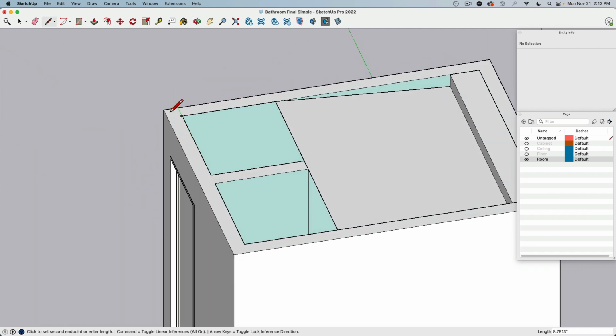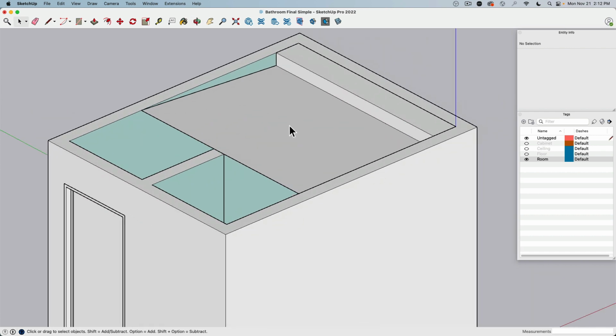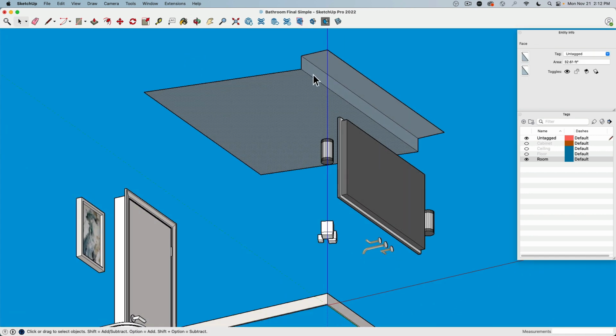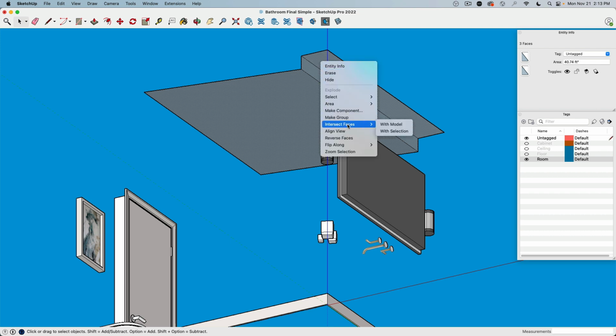And yeah, I actually, hold on. I have one line here I delete. And then this, for example, I would like to texture. You see, this is actually white right now. So this wall I will hide, so I can rotate my view. You see, this is actually blue. These faces, right click, and then reverse faces.